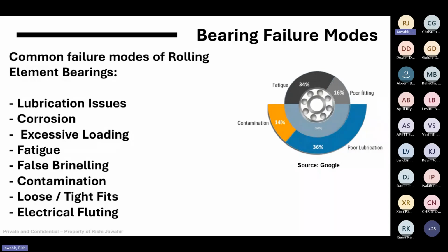So what happens now, sometimes our bearings are not properly grounded and there may be an electrical short. The electricity or current will flow from the equipment, especially motors, right? And actually flow through the bearing to ground and causes what is known as fluting, where you see actual indentations around the race of the bearing. And this is common, this actually happens a lot. What has to be done is proper shaft grounding, also ensure there are no stray voltages. And there are shaft rings that can be installed to reduce those shaft voltages. There are insulated bearings that can be installed to reduce this electrical fluting, right?